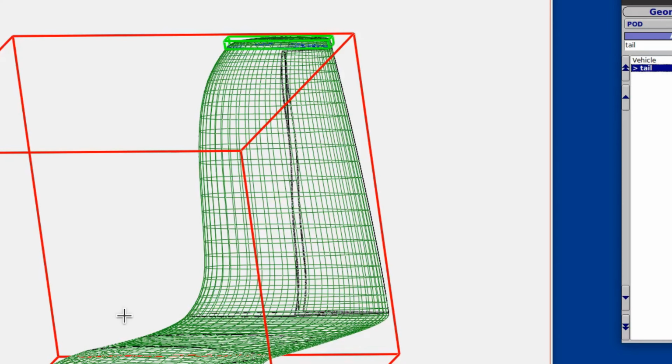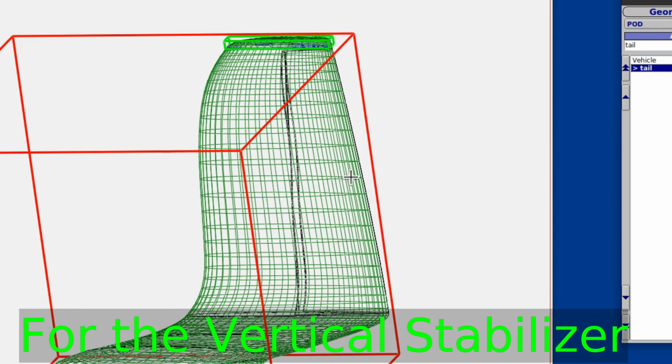That shear force or shear load will be greatest wherever your flying surface is held rigidly, and it'll be least wherever your flying surface has the most freedom of movement. The shear load is 0 out here toward the tip, and as you get closer and closer to the root, the shear load increases.